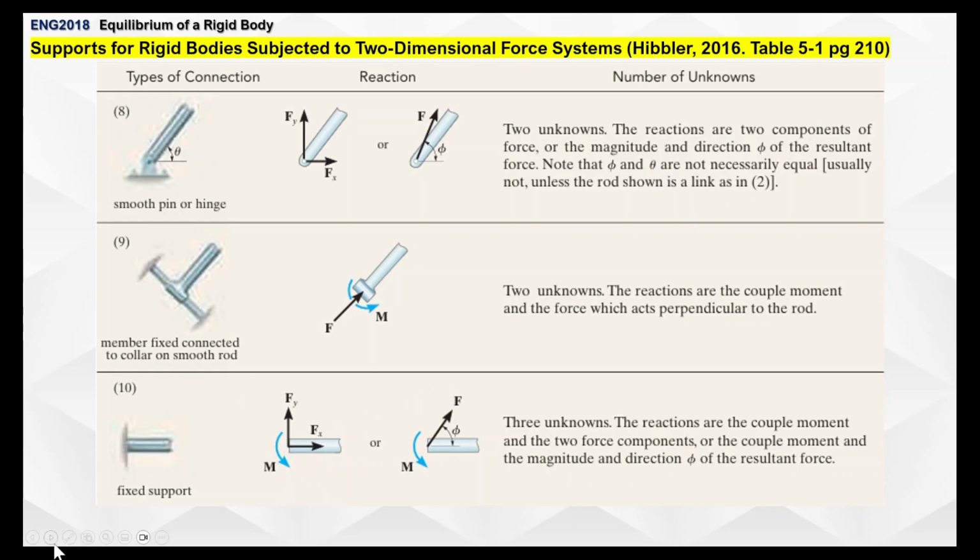Notice that the default representation of the forces here is on the positive side. So we're going with right for the horizontal force Fx as positive, going up Fy as our positive, and then counterclockwise moment as our positive. Once we solve our equations of equilibrium, if it yields a different sign, meaning our representation in our free body diagram was wrong, or our initial assumption was wrong. But we will get to that later.